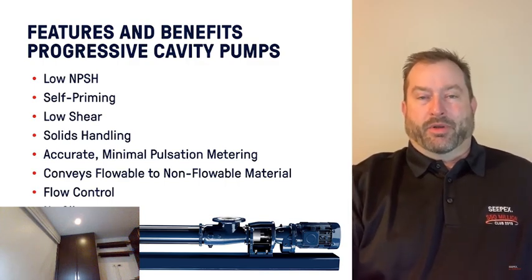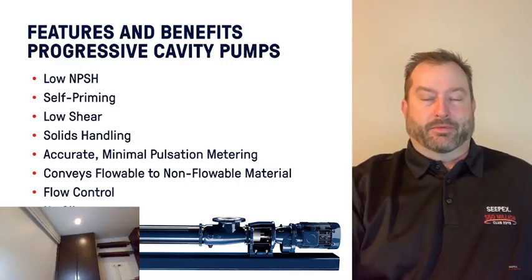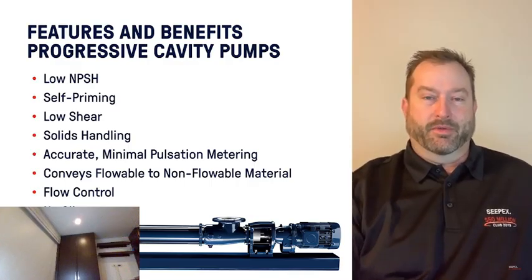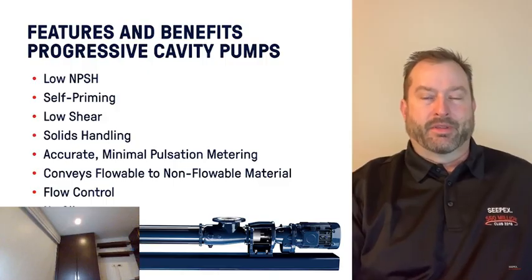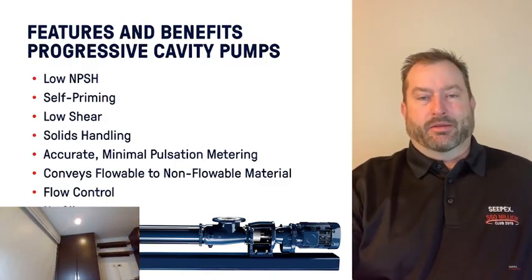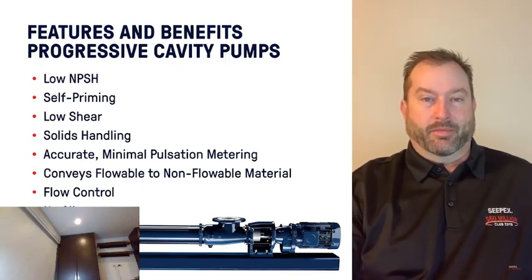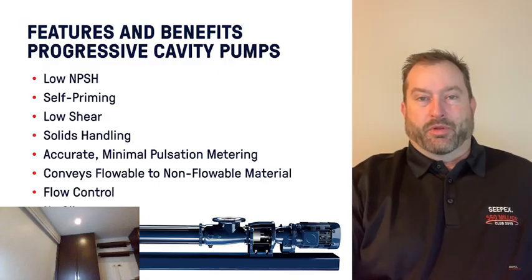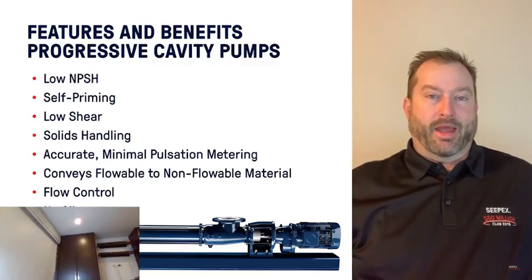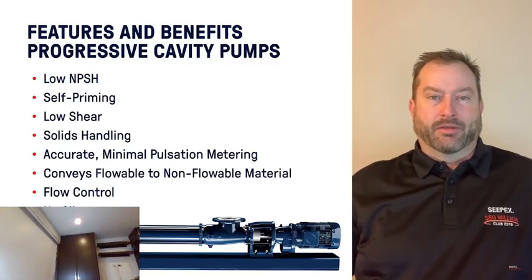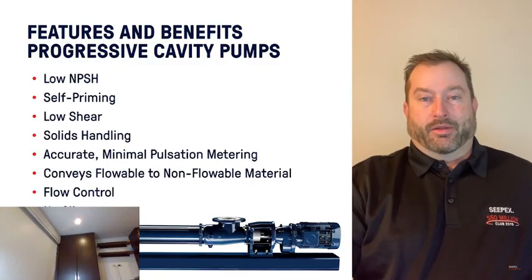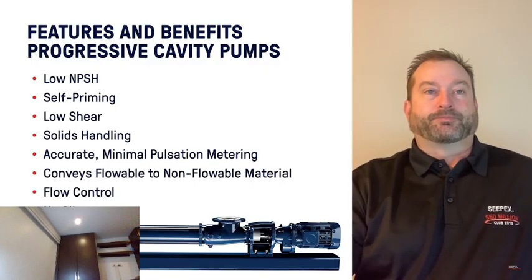Pumps can also operate in either direction. So the normal suction is coming in at a 90-degree angle to the pump, and the discharge is out the end. We can actually reverse rotation to where the suction is coming in the straight component. A lot of times if we're pulling a suction lift, we will actually run the pump in that direction so the seal or packing is not in the suction casing. We can pull higher lifts in that configuration.